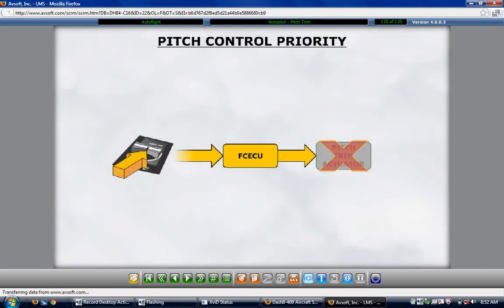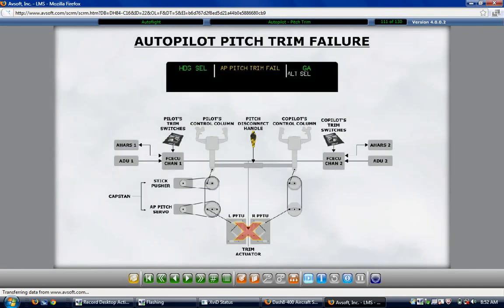During autopilot engagement, each flight guidance module monitors the autopilot pitch servo torque. When the pitch servo torque exceeds a certain limit, the flight guidance modules will display an amber mistrim trim nose up or mistrim trim nose down message on the primary flight display. The pitch mistrim message is removed from the primary flight display when the autopilot pitch servo torque is reduced below the trigger limit. The pitch mistrim message is not set by the automatic flight control system when the autopilot is disengaged or when tactile control steering is active.